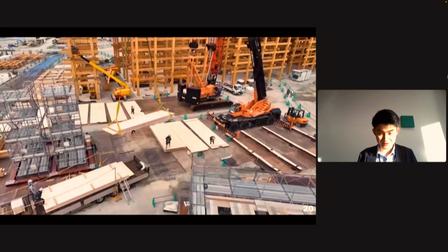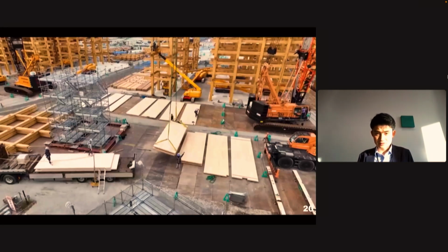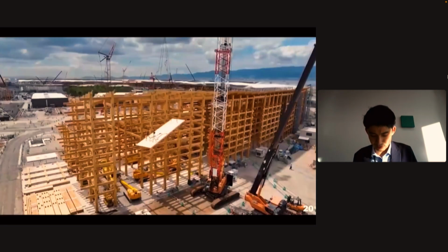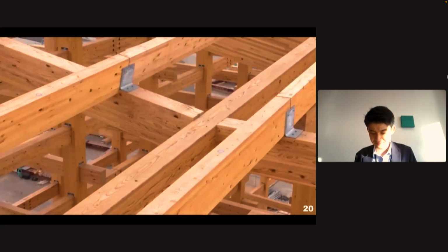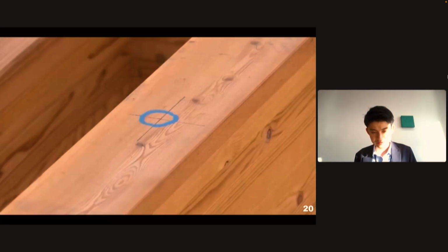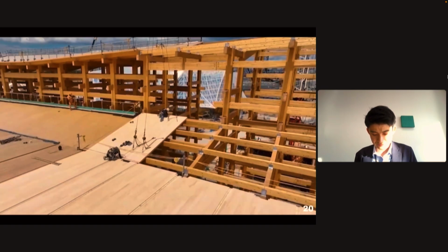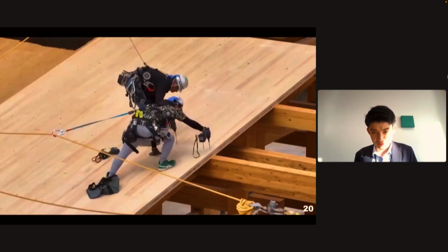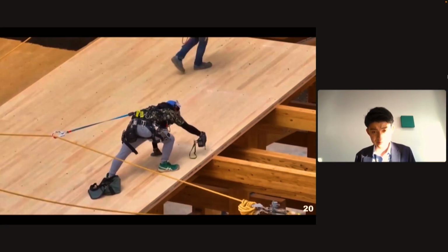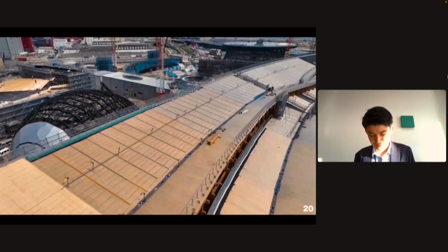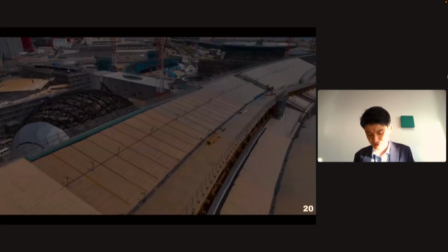Then install CLT panels. Each panel is 2.4 meters by 8 meters, about 20 square meters per piece. We press them onto the ring frame and drive a long screw into the beam. By this process, precision plus unitization plus repetition, the ground ring takes shape.